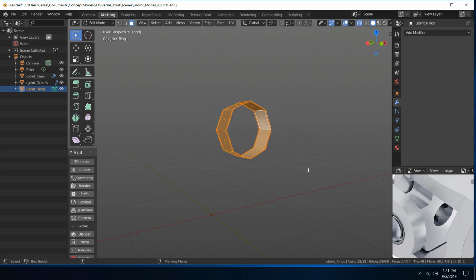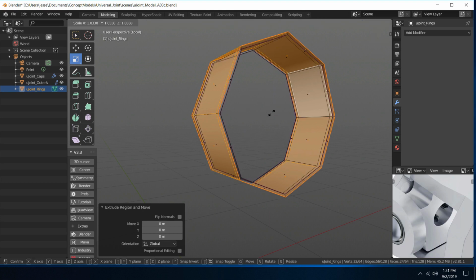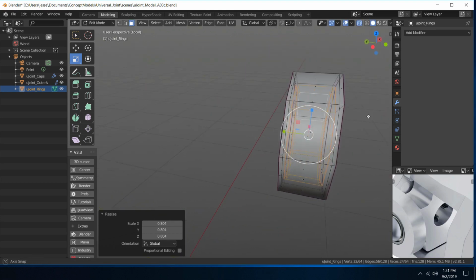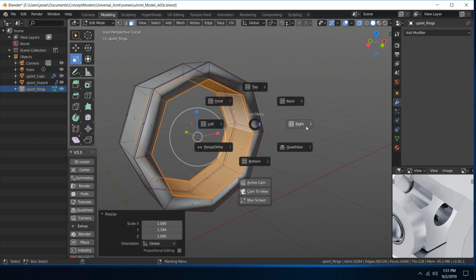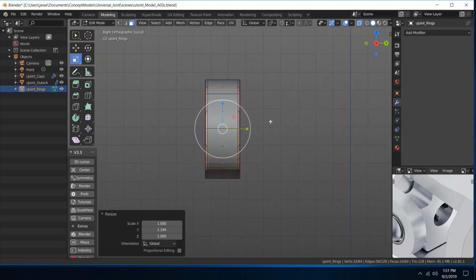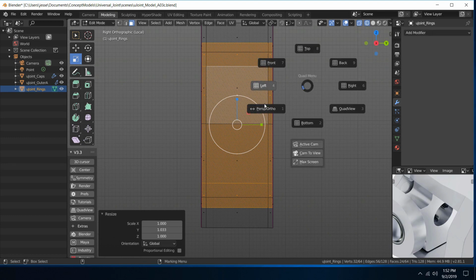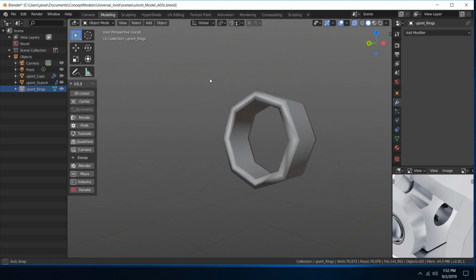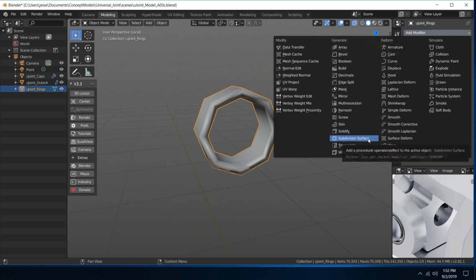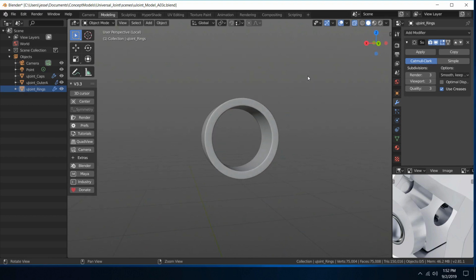and let's come over here and delete all those faces, and then grab all these faces again, Control E to extrude, and now we'll just hit escape, bring up our scale tool and drag in. Then pull out a little bit. We can bring up the quad menu and look at the right and perspective. Line it up. I have it on a wireframe there. Okay, so spacebar and back into perspective. Now let's go ahead and add that subdiv surface. Alright, so that's looking pretty good. And hit Alt E.